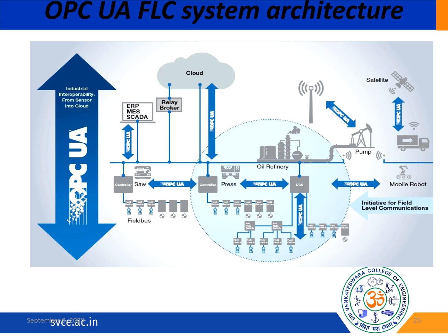Each field device and fieldbus ensures sensors and actuators collect real-world process data. And here we have the advanced physical layer, which is considered APL. The advanced physical layer switches connect the field devices and integrate them into the network. OPC UA enables standardized communication from these devices upward. It moves upward to a controller, where we can have the DCS level.